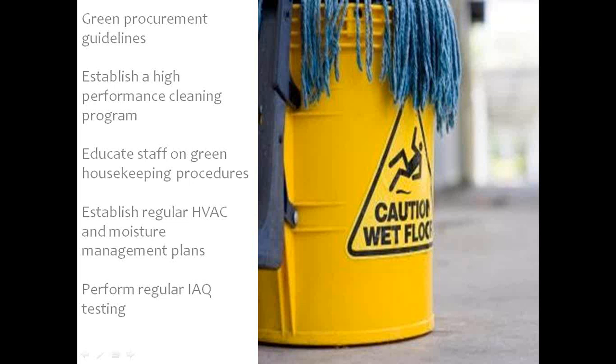You can put low-emitting products in, you can have it built properly, but then if somebody comes in at the end of the day and cleans with solutions that are full of chemicals, you've simply negated all the hard work that has gone on before. So educating people on how to use the cleaning products, meaning application, is important. As an example, we use a lot of aerosol products today. When you spray an aerosol product, you're simply creating thousands of tiny droplets that can now be dispersed through the air. Better application would be to apply a wet product directly to a rag and then use that to wipe down the surface.